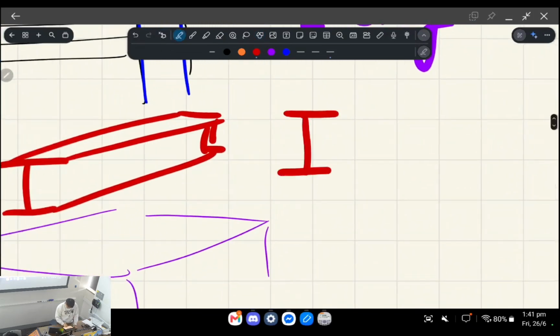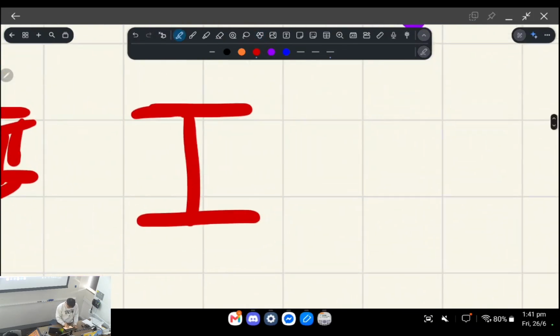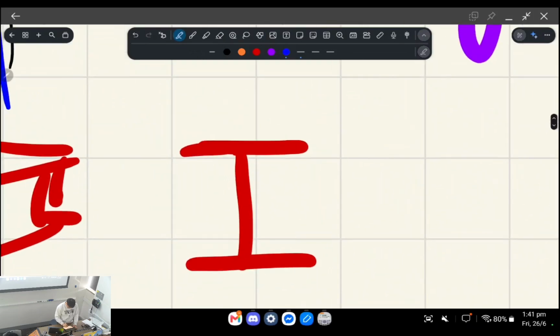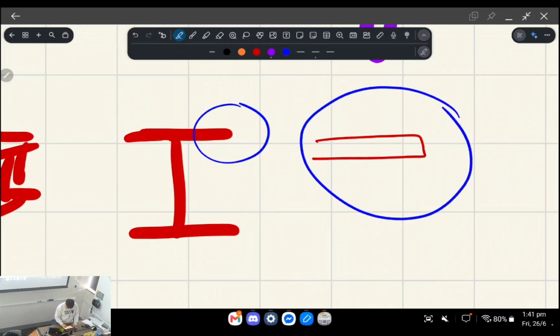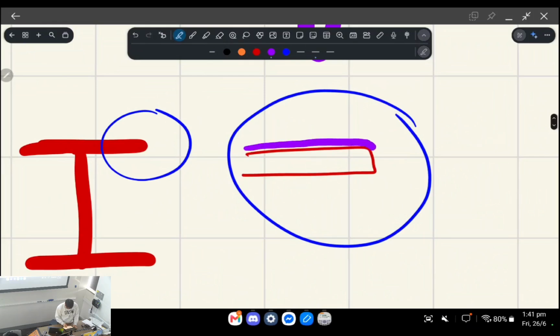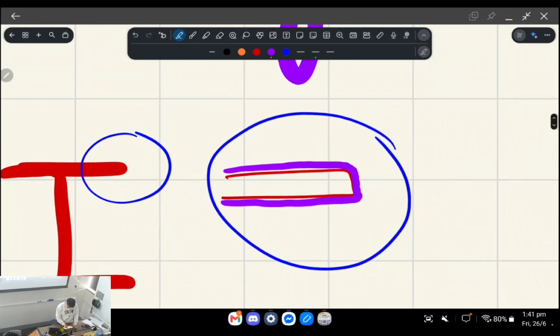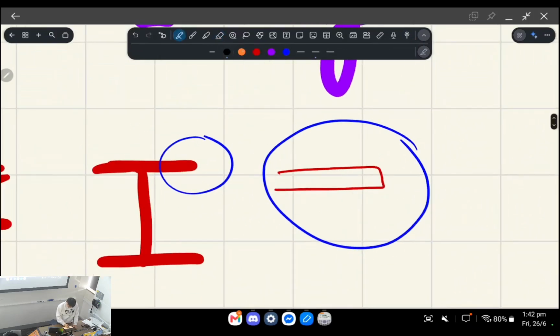The cross-section of this mild steel beam looks like so. And what's really interesting is if I zoom into here, for example, the top flange, the galvanized layer has a very uniform thickness. Literally the crystals form so it has a consistent thickness around these sharp bends, which is pretty cool. Why is that different to the first method, the fusion bonded epoxy?